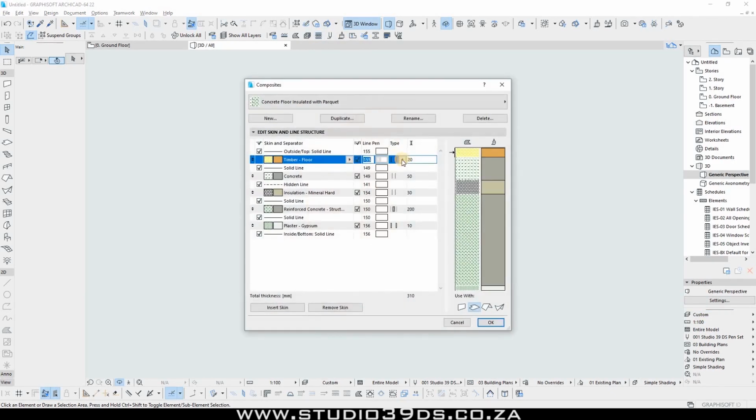So basically that's how you do it. If you want this to be a core, or if you just want it to be a finish, you can depict it as you wish. It's best to use core for all load bearing elements, and finishes for things like gypsum board, ceilings, or plaster. And then the rest can be other, which is pretty much not as important, like insulation or something like that.